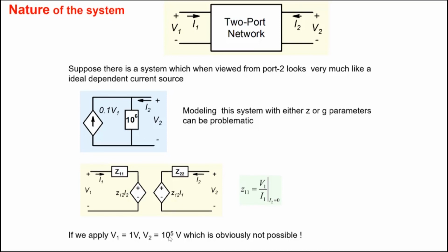So what it is saying is that you cannot open circuit the output terminal here. If you open circuit the output terminal in this case, a very high voltage will try to develop, and the system may get damaged here.